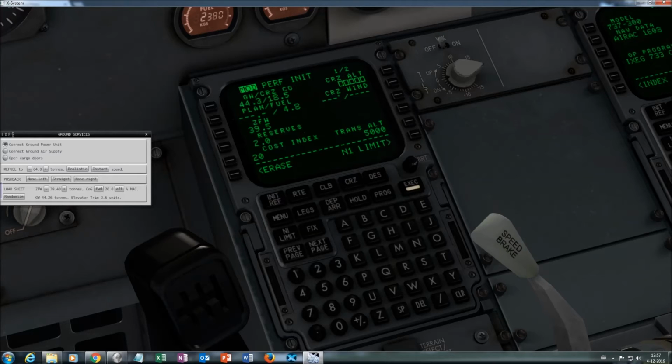And you can tell the computer which you want by entering a number here. And I don't have the entire formula. If you want that, look it up. It's probably to be found somewhere. I don't know it, and I don't really want to know it. But I do know that KLM uses in the 737-300 a cost index of 30. So I dial in 30. And now the flight management computer will calculate with the formula where the cost index variable is set to 30. So it's reasonably fuel efficient, but not too slow.